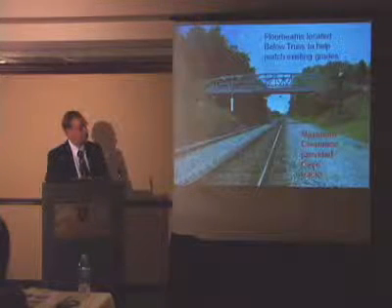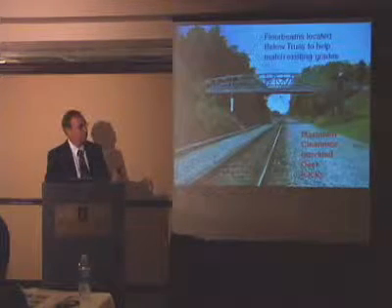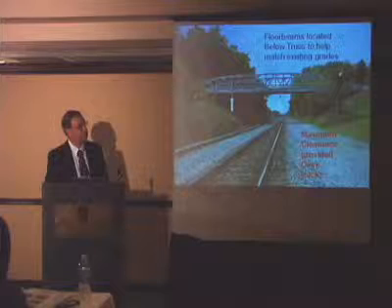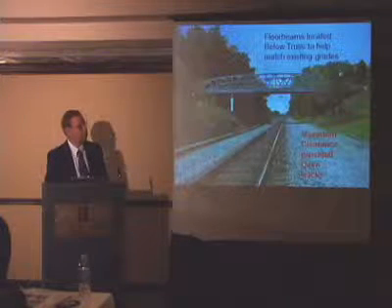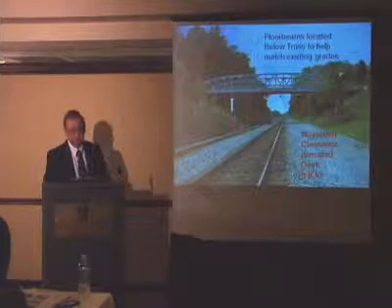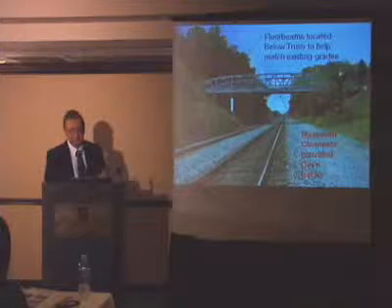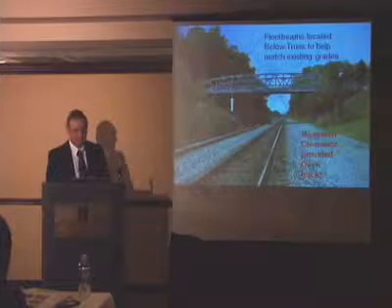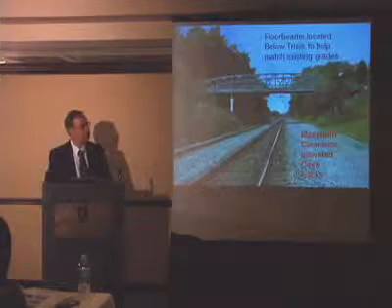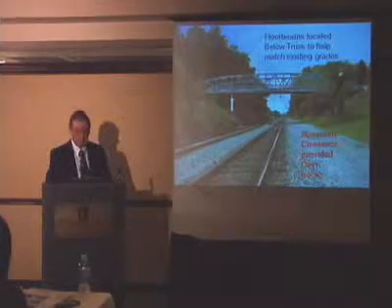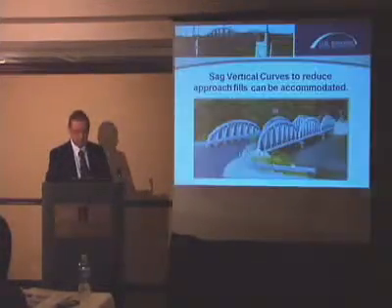In this condition, they had to increase the height maybe a foot or so at the end, but they only tapered it out within 50 feet of each end of the bridge. So it saved the county a lot of money on approach roadway work.